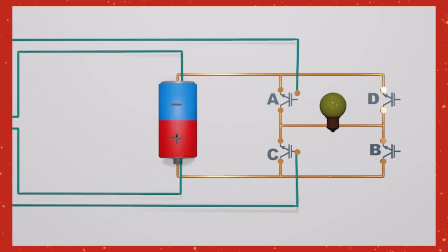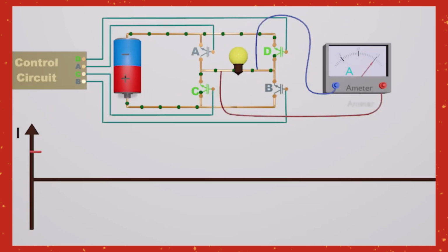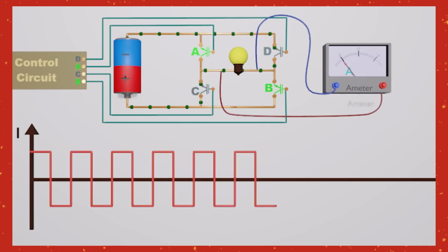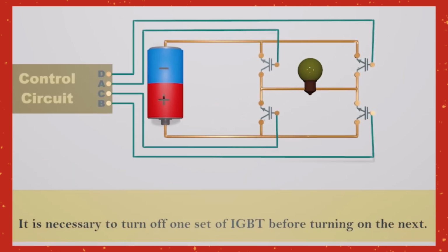AC square waves are very abrupt and can end up damaging some delicate electronics in your home. To solve this, manufacturers invented rectification devices that modify the wave, creating what is known as a modified sine wave, MSW. As the name suggests, a modified sine wave is not really a true sine wave at all. It is simply a stepped wave, like this. While MSW is better than a square wave, it is still not a pure sine wave, which is required to power certain delicate electronics.